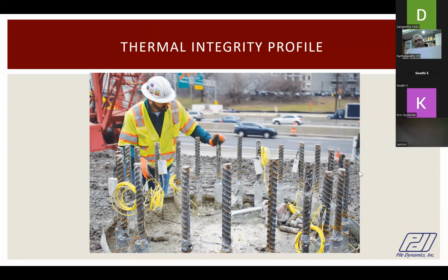Okay, so thermal integrity profile is a newer method of evaluating the integrity of deep foundation elements. Like CSL tubes, you have to embed the thermal wires. The yellow ones you are seeing are thermal wires which run all along the length of the reinforcement cage. And these thermal wires have thermal sensors. You could see these are the thermal sensors, and another 1 foot away you have another sensor. So thermal sensors are there at every 30 centimeters, 1 foot.